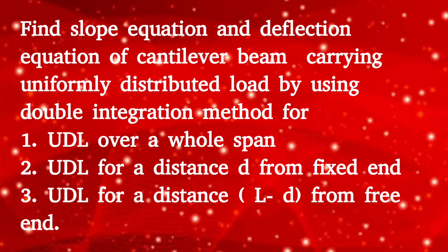Given the question, find the slope equation and deflection equation for a cantilever beam carrying a uniformly distributed load by using the double integration method: first, UDL over the whole span; second, UDL for a distance d from the fixed end; third, UDL for a distance L minus d from the free end.